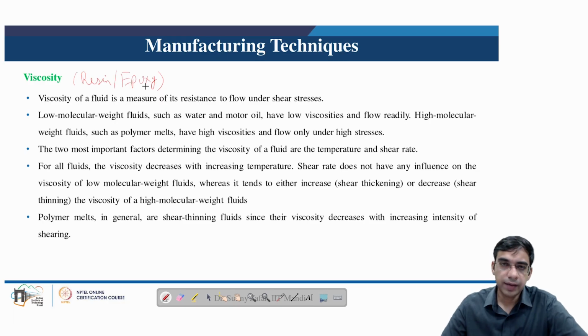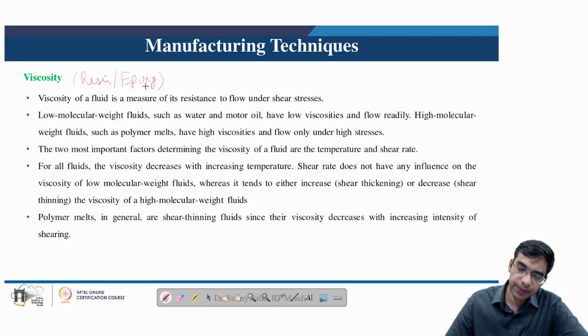Shear rate does not have any influence on the viscosity of low molecular weight fluids, whereas the viscosity of high molecular weight fluids may increase because of shear thickening, or decrease because of shear thinning. Polymer melts, in general, are shear thinning because their viscosity decreases with the increased intensity of shearing. And as we have discussed previously, for the thermosets, the viscosity first decreases.